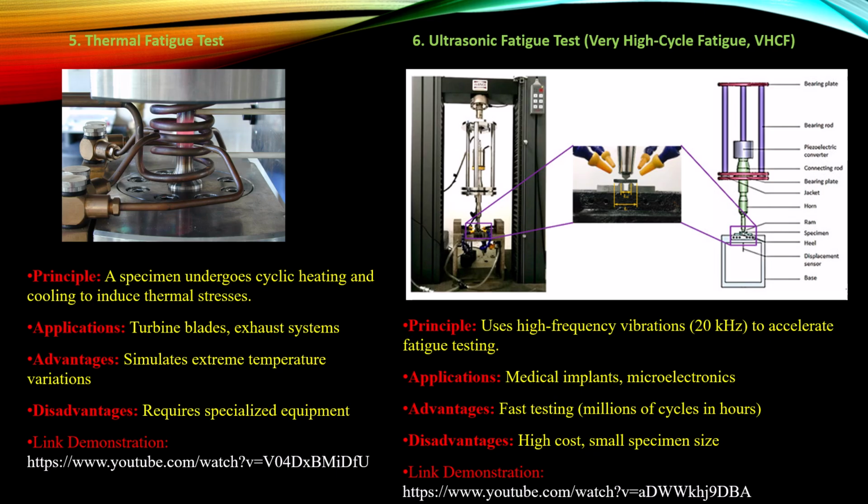introduces the ultrasonic fatigue test, also known as VHCF. That stands for Very High Cycle Fatigue testing. This advanced method utilizes high-frequency vibration at 20 kHz to dramatically accelerate the fatigue process. It's particularly valuable for assessing medical implants and microelectronics that must endure extreme longevity.